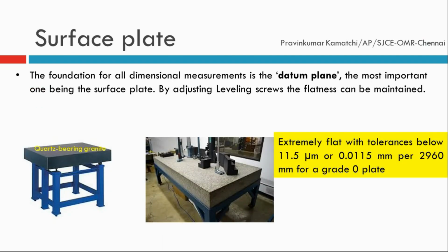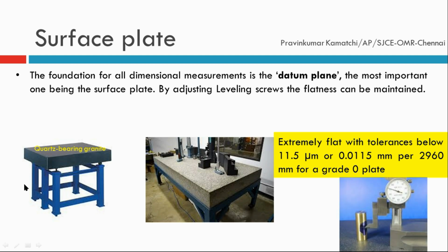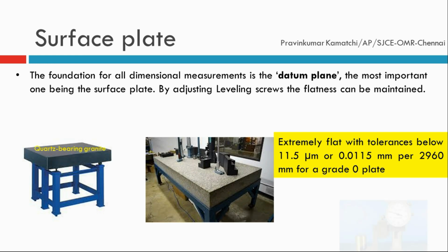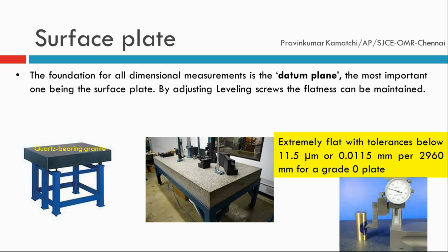Surface plate. Basically, linear measurement starts at a reference point and ends at a measured point. This is true when our basic interest is in measuring a single dimension, that is length in our case. However, the foundation for all dimensional measurement is the datum plane. It is a very important one. One example is the surface plate. With the help of adjusting lever screws, we can ensure the flatness of the surface plate.